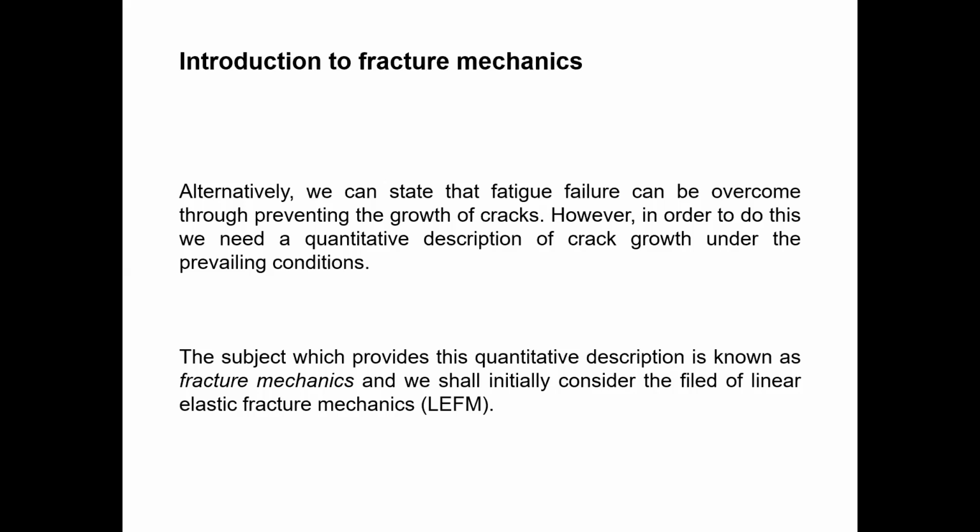So for the theory behind this, we will only consider the linear region. That theory we call linear elastic fracture mechanics. Okay. So we will discuss only the linear region. You know what is the meaning of linear region? Elastic region. Okay, we are not going to the plastic region. So in the elastic region only we will deal. So it is the elastic region fracture mechanics theory. There is a specific theory, and we will use that theory to quantitatively analyze the crack growth.